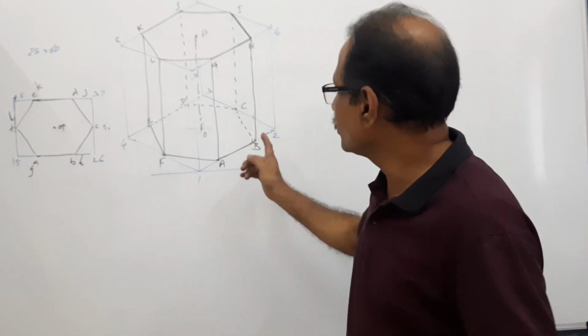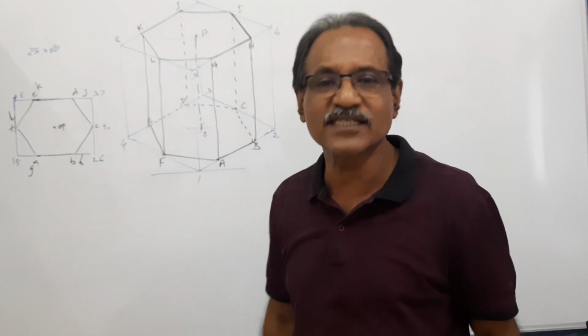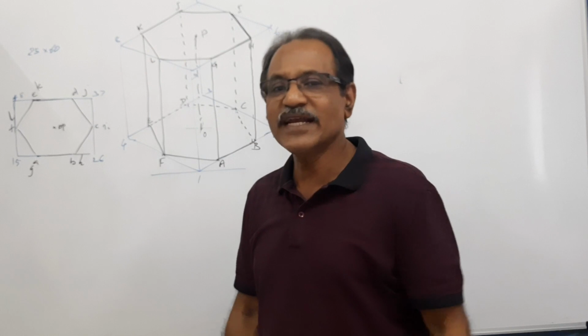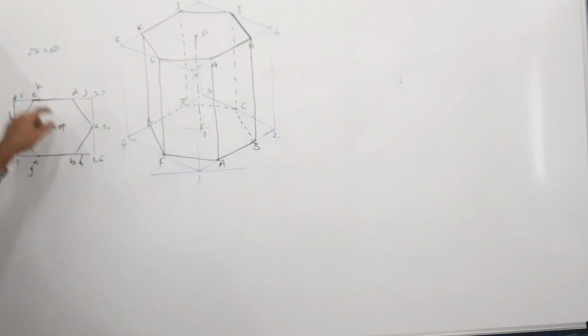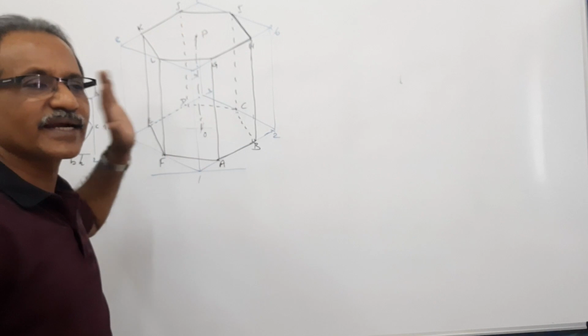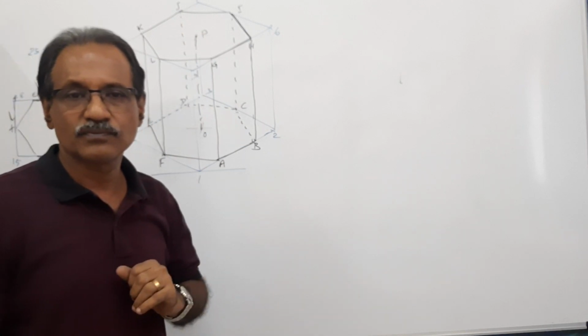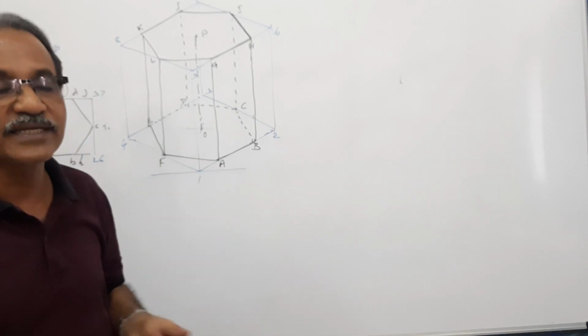But you have to be careful, the box, the blue lines, the box must be very light because such a box doesn't exist. Okay, when it comes to a pentagonal prism, you do exactly the same thing. Draw a pentagon, inscribe it in a box, draw the isoview of the box, inscribe the pentagonal prism inside the box. Agreed? Inscribe the pentagonal prism inside the box.